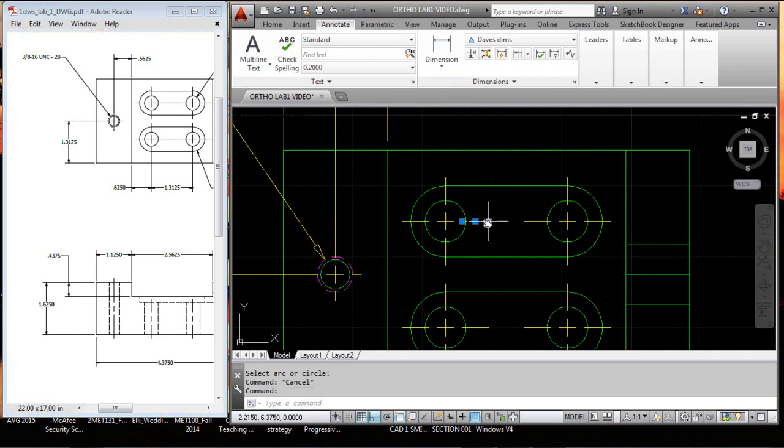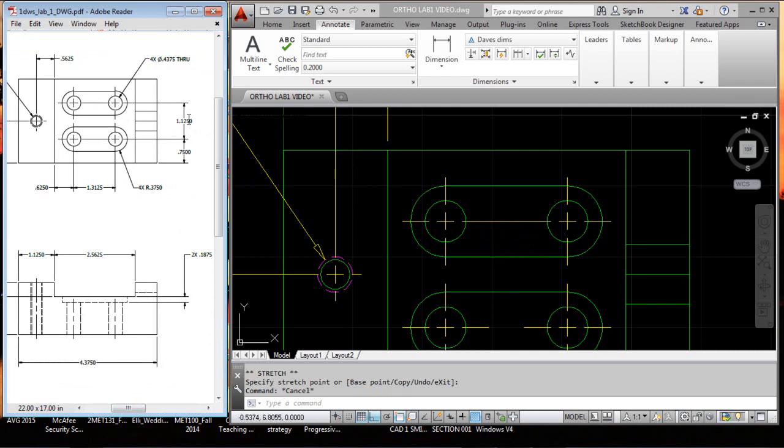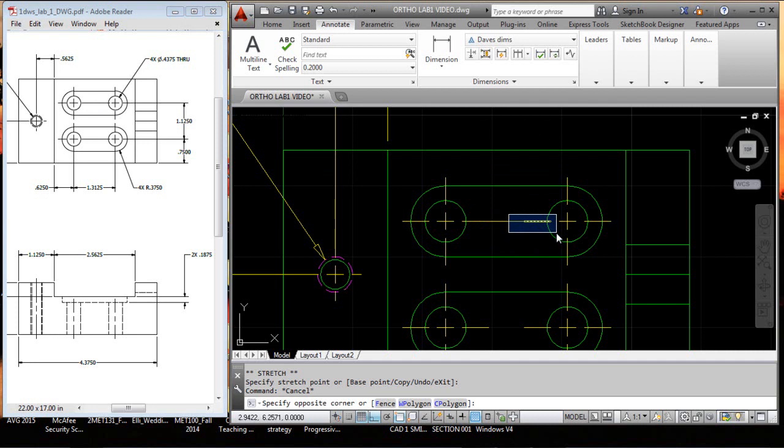Now in Inventor, and we can do it here, notice these are all separate lines now. It puts them in as a series of lines, but what we want to do is take this line and grab it and go over to the other end of that line. That extends that through, and that we're allowed to do. If we don't extend that through, then we would have to put 2 times right here. It happens here and it happens here. But since we extend the line all the way through, then it's understood that these are on the same line, if you will. The only thing I want to do though is go back here, put a window around that, and delete that line.